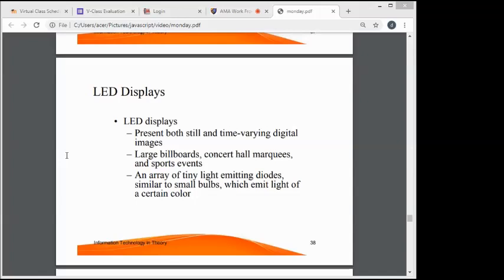So an LED screen is actually an LCD screen, but instead of a normal CCFL backlight, it uses light-emitting diodes as the source of light behind the screen. An LED is more energy efficient and a lot smaller than CCFL, enabling a thinner television screen. Marketing made a lot of fuss about LED TV, but it is only the backlight that changed, so there is actually no picture quality improvement over a normal LCD screen.